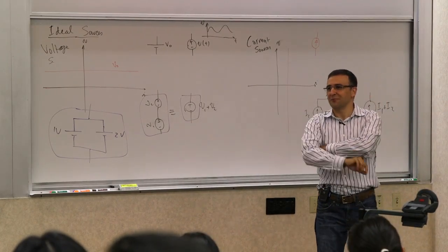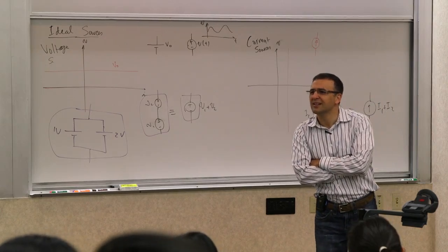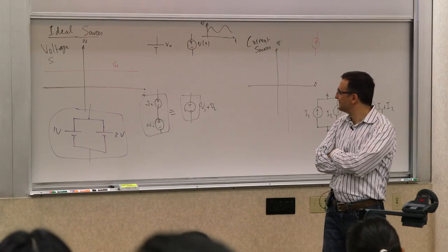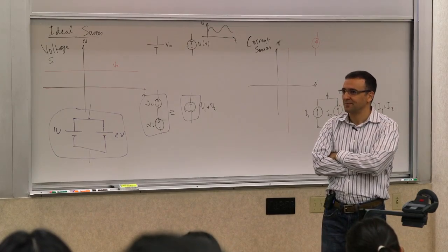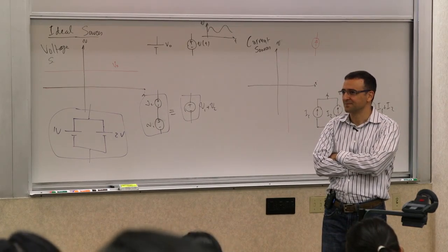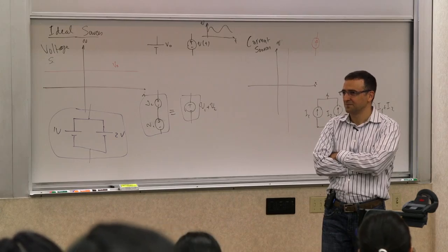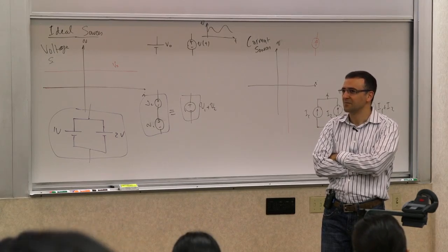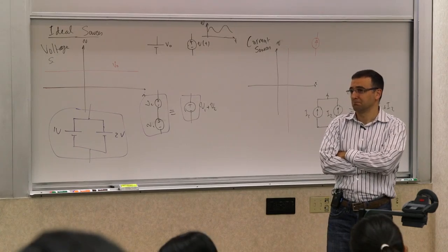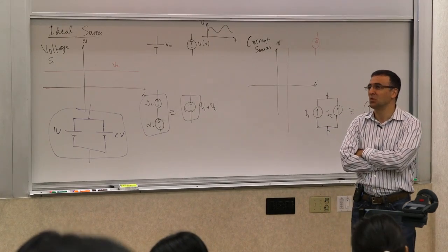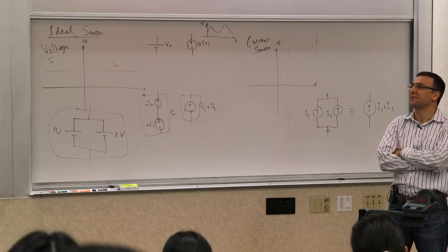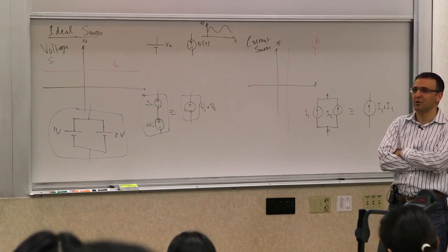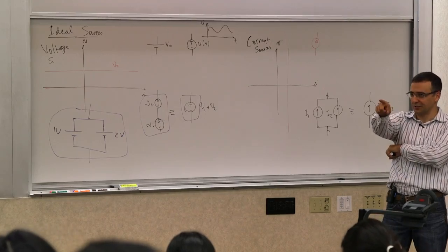There are two more, and then we'll get to it. Will, okay. Well, the problem is that you have a short circuit on both the top and the bottom, and on the IV curve both voltage sources are trying to establish a different voltage across the short circuit. But the short circuit can't have a voltage across it. The voltage sources are going to start competing. Okay. The 1 volt is going to sink a lot of current. The 2 volt is going to provide a lot of current. Sure, there's some sort of a problem. You're observing a problem, right? Good observation. Hold that there.